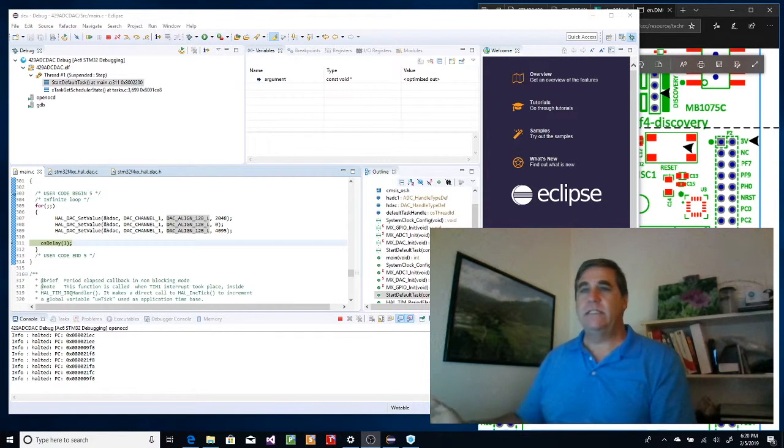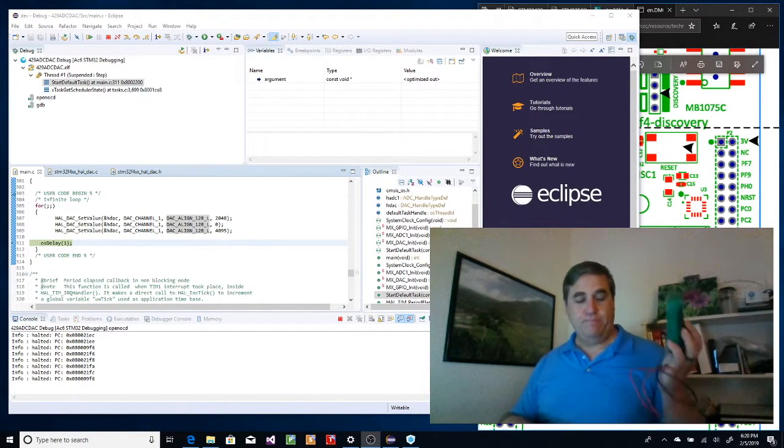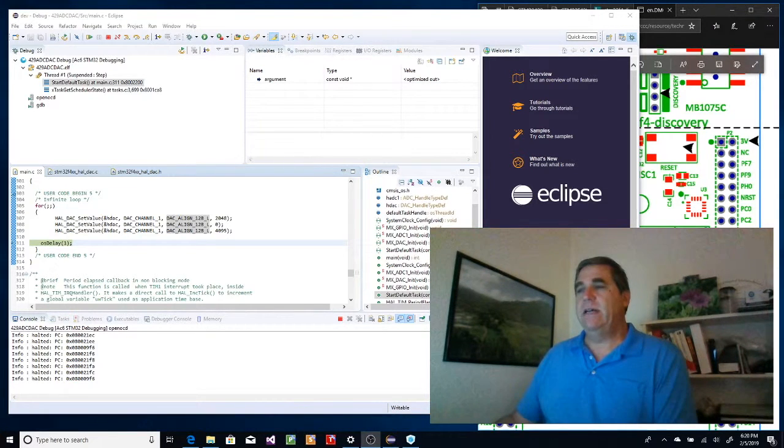But for now, that's a DAC, just the simplest case, which is to put a value into a DAC to see a readout on an analog. I just used my meter to look at the output on the pin, and I did get 0, 1.4, and 2.8, but it did what I expected. Happy with it. Didn't use any interrupts, didn't use timers or anything like that. Just the simplest, set a value. Okay.